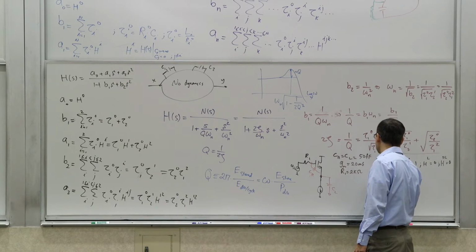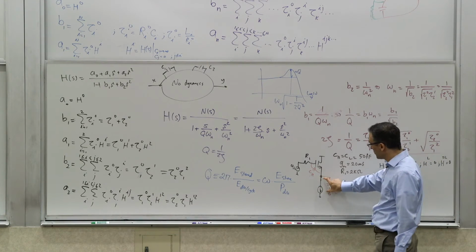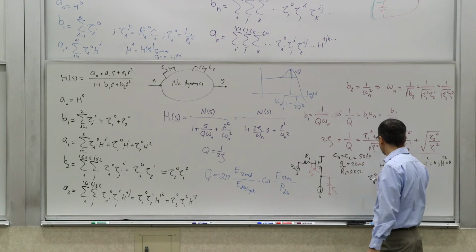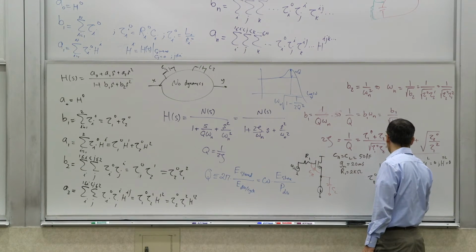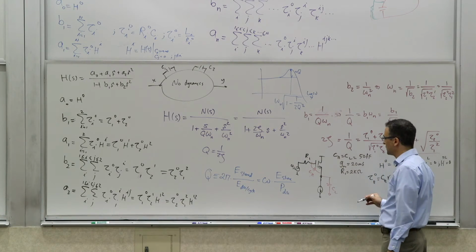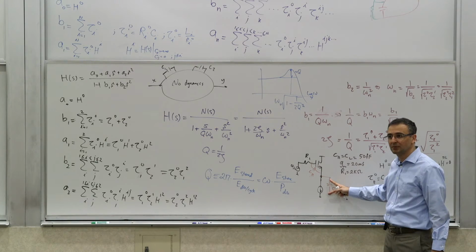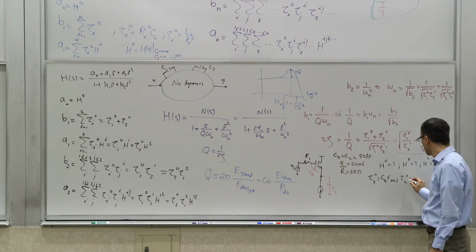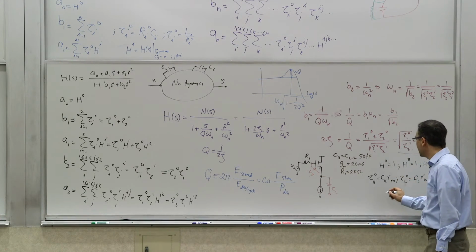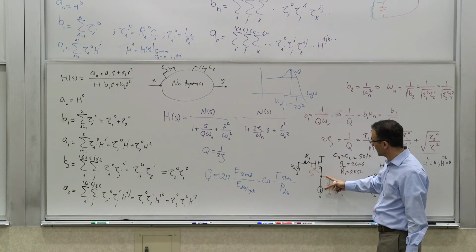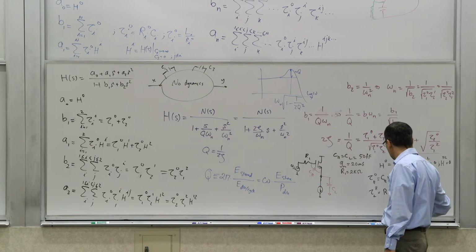The time constants: tau pi 0. Now you don't have a resistor here, so all the current has to circulate, so it's the resistance seen by it, Rm. So it becomes C pi Rm. Tau L0 is what? What is the resistance seen by CL when this one is open? It's also Rm, looking into the source. So it's CL Rm. And you need one more; you can pick the one that you like. I would say tau L pi. If you just short circuit this, it sees R1, so it's CL R1.